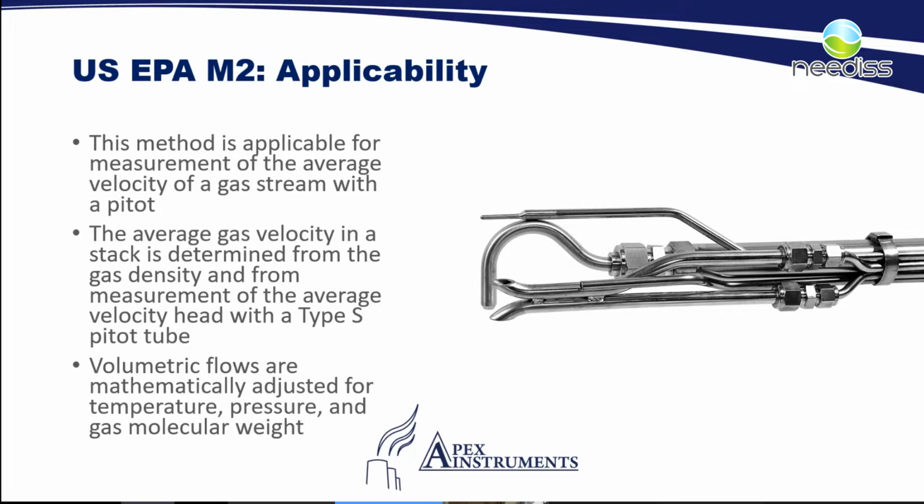And then as you know, the volumetric flow rates are adjusted mathematically for temperature, pressure, gas molecular weight, variables that can be standardized to then allow us to compare stacks of different temperatures or pressure against each other against a standardized volume that we've determined from our flow rate.